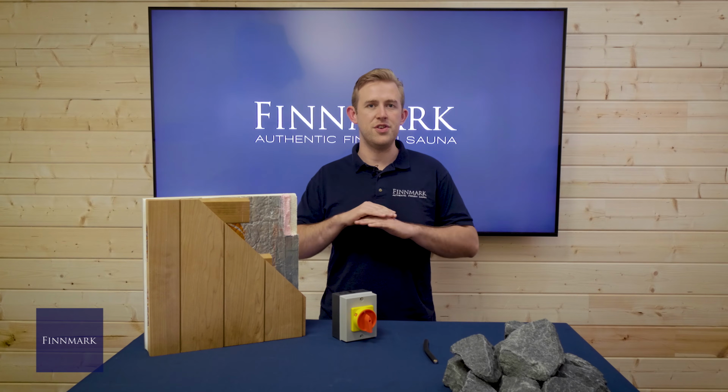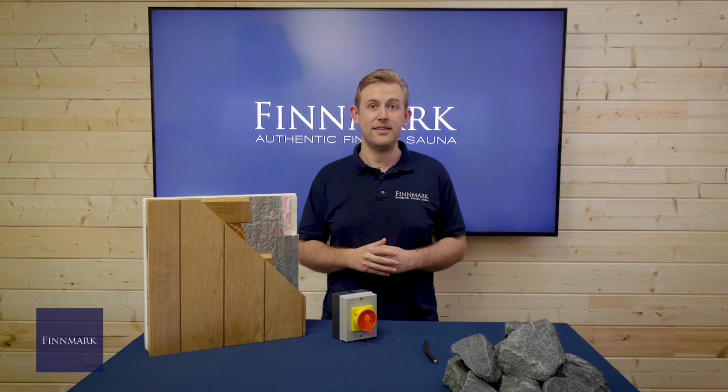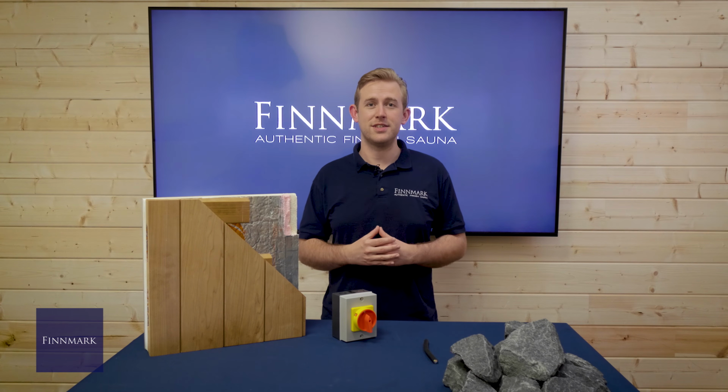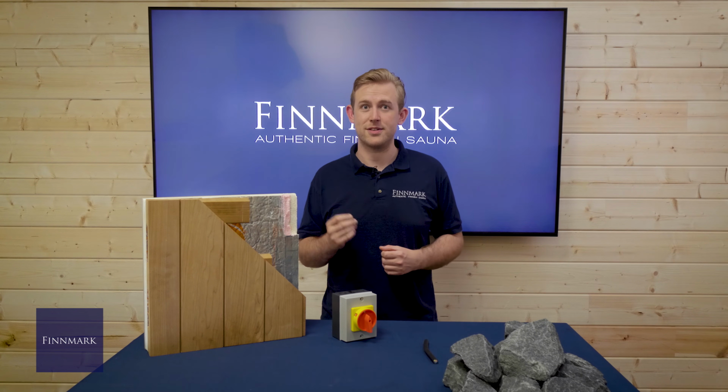Standard PIR insulation boards are not safe beyond 60 to 80 degrees Celsius, after which they begin off-gassing hydrogen cyanide, which is highly toxic. Kingspan Sauna Satu and FinFoam act as both your insulation and your vapour barrier.